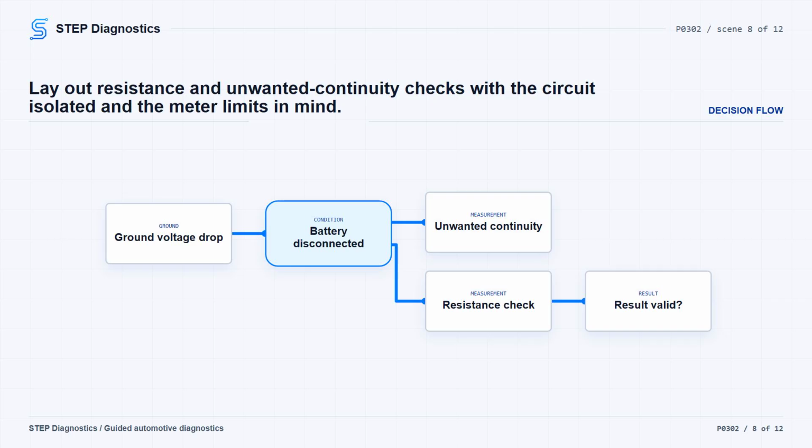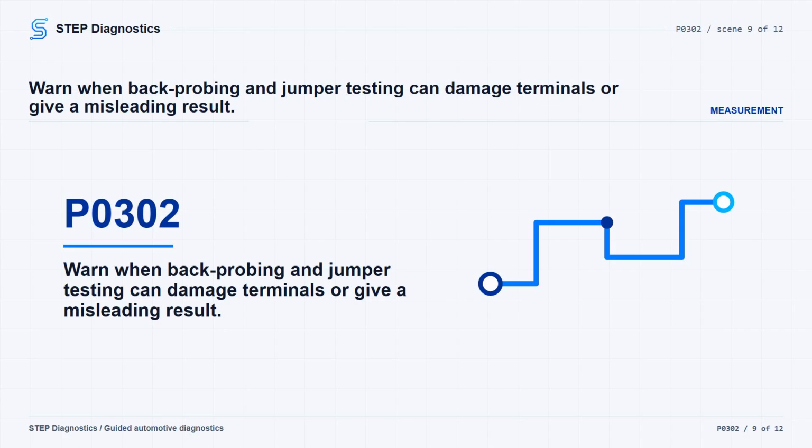Again, resistance should be greater than 10,000 ohms. To check for unwanted continuity to a powered circuit, disconnect both ends, turn ignition or run power on, and measure voltage from the suspect circuit to ground. Only back probe when the circuit has to be tested under actual operating conditions, or when voltage drop testing requires it. Normal voltage drop testing should show a small amount of voltage, with less than 5% of circuit operating voltage expected. Do not force test leads or probes into connectors, and use back probes made for that job.